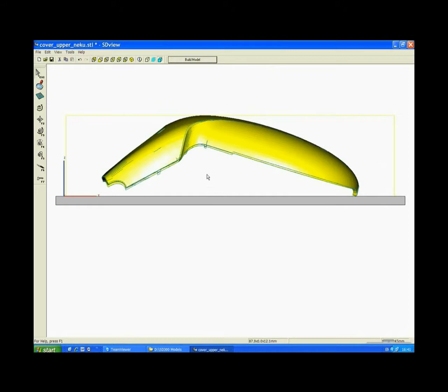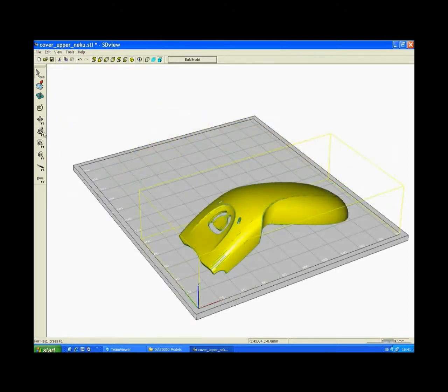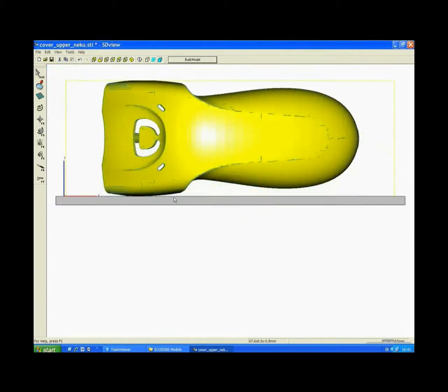We will now rotate the part. Select the x-axis at 90 degrees and rotate the part. Now, layer direction will be from bottom to top. Features such as the functional button will get their strength from the layer direction.